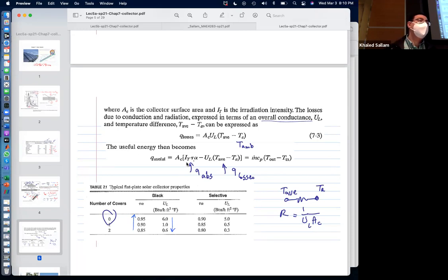Okay, what is I? The incident radiation. The watt per meter square falling on our collector because of the tilt, because of where the sun is, because of how hot the day was. At the end of the day, you get a table that tells you how much incident radiation there is in Tulsa, Oklahoma, during a certain day. And so for the project, we can make it really long and say, well, let's calculate this for every single day of the year. And then you will hit me and you'll hit yourself and you'll hit the course. Or just to prove that you know the calculation, we can base the whole year on one day. So this will cut your work, but it just shows me that you know how to do the calculation.